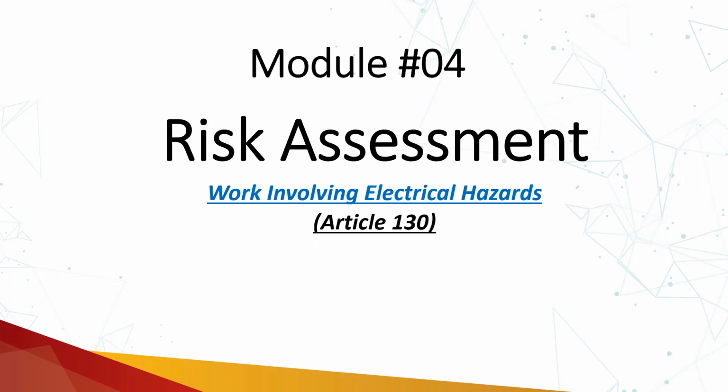further. For example, the initial risk assessment informed that there was an incident energy of 24 cal/cm², and the voltage level was, for example, 11 kV, so you wear personal protective equipment rated for that particular voltage level, and also for that incident energy of 24 cal/cm². Once you have established an electrically safe work condition at location B, where you will be performing some electrical tasks, at location B you don't need to wear that 24 cal/cm² arc flash suit and the gloves of 11 kV.